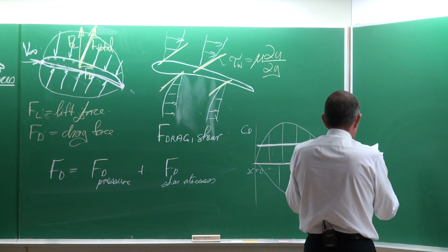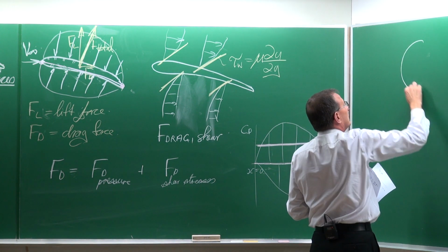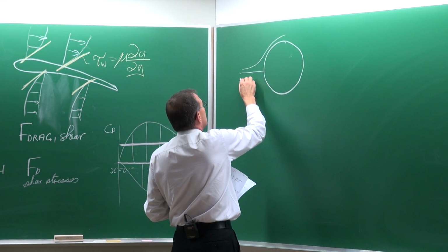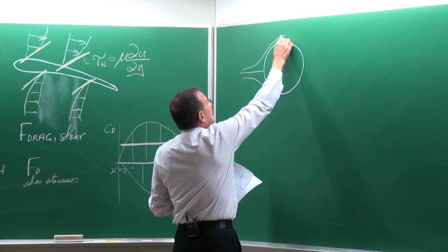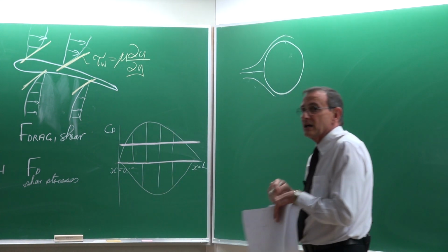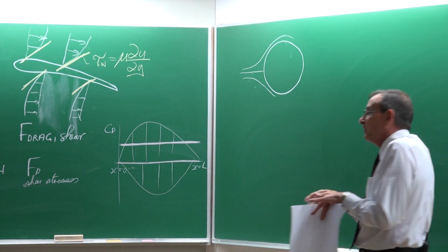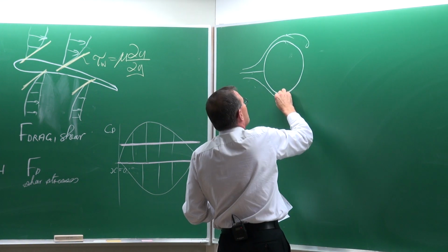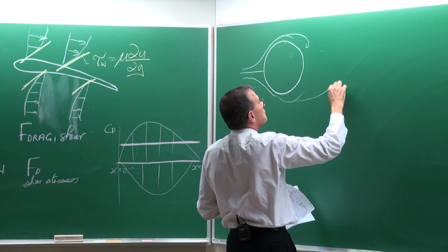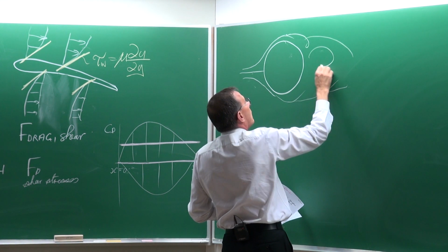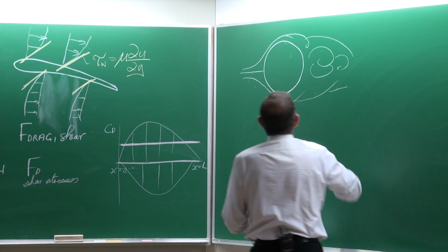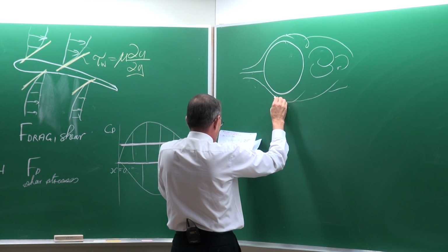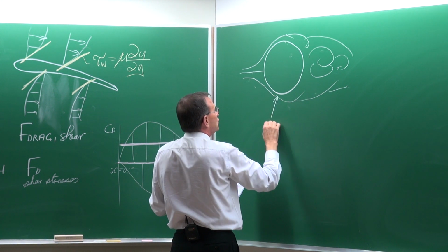Now in fluid mechanics, you would also know that if you look at, for example, the flow around a cylinder, then the flow doesn't, in many cases, follow the geometry perfectly. It would separate from the body. And here at the back, we can have very complicated flows, and we would call that the flow separation point.